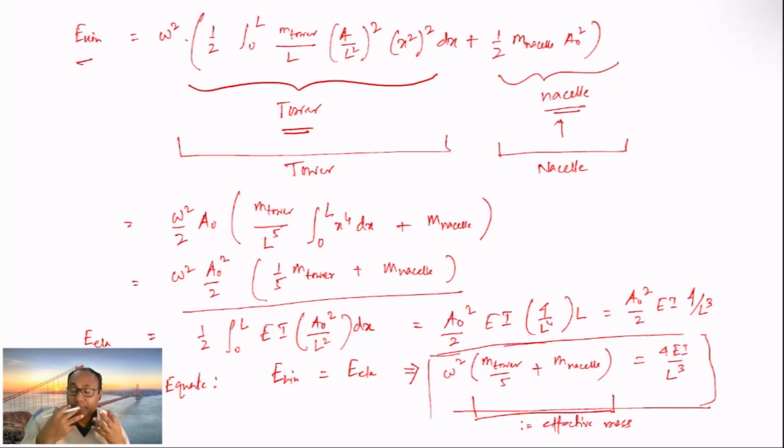And why are these important? Because these are important to estimate the frequency of oscillations and then find out what could be the natural frequency of that structural element. And since these are exposed to wind loading, there could be effects, or I would say the structural design consideration would be very, very important.